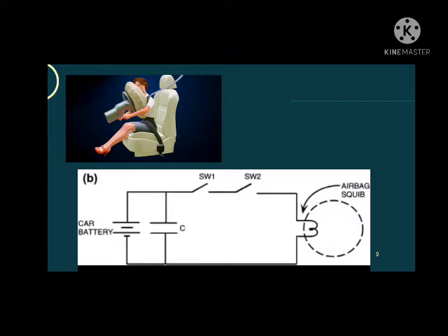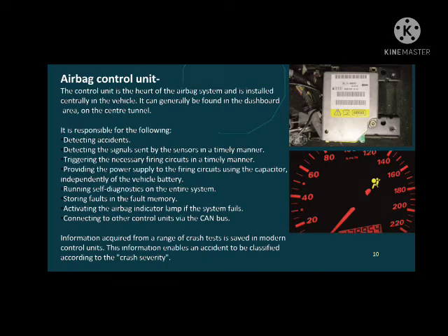Referring to the sketch in the figure, the operation of the acceleration sensitive switches can be understood. Under normal driving conditions, the spring holds the movable mass against a stop and the switch contacts remain open. During a crash, the force of acceleration, actually deceleration of the car, acting on the mass is sufficient to overcome the spring force and move the mass.